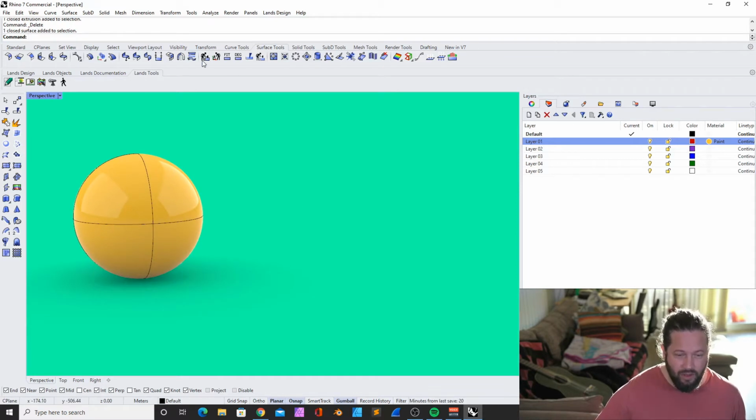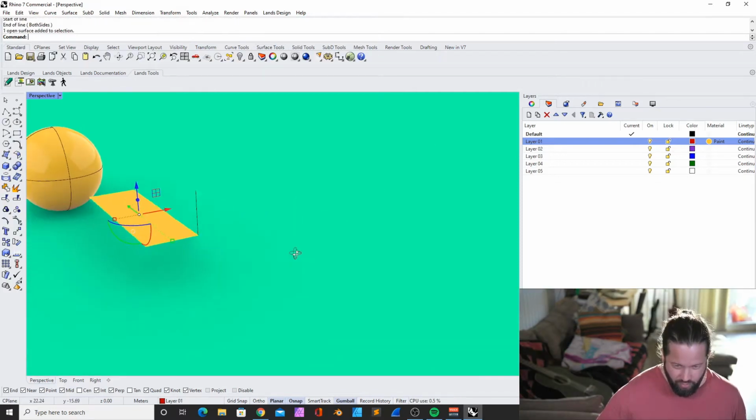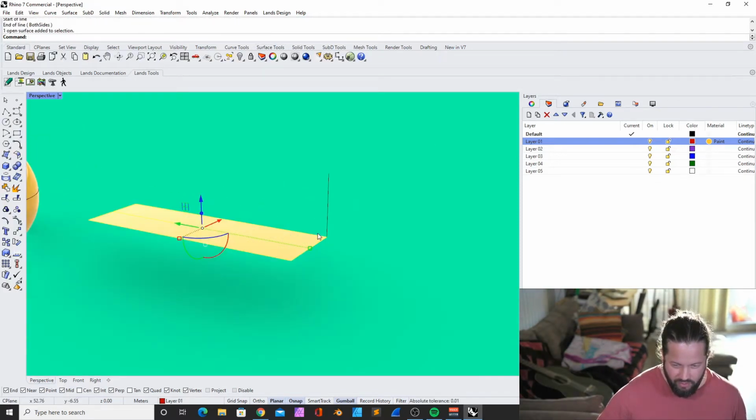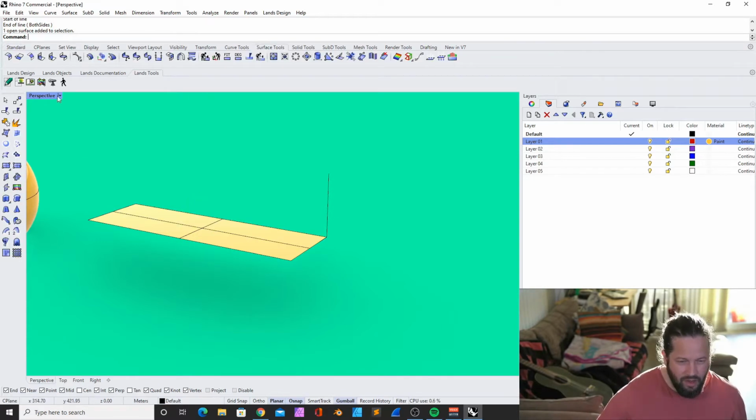And now we jump into this section here. These 1, 2, 3, 4, 5, 6, 7 tools we will look into very quickly and right now. First of all, we have set the surface tangent direction. So here we have a surface, and if we want to bend our edge, we want to set the edge direction to that line, then we can use this tool. I will stay here, and it's pretty straightforward, but we will discuss the problems with this and how we can fix it.